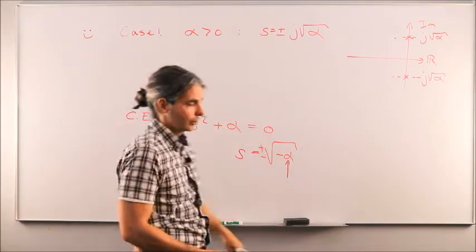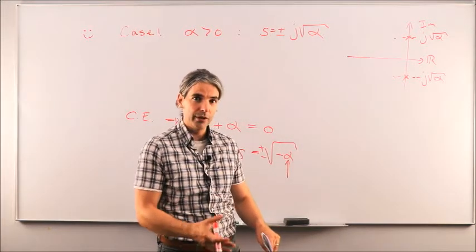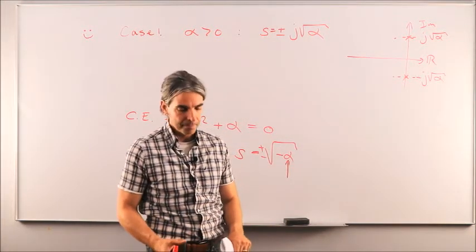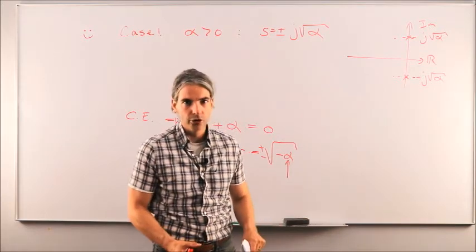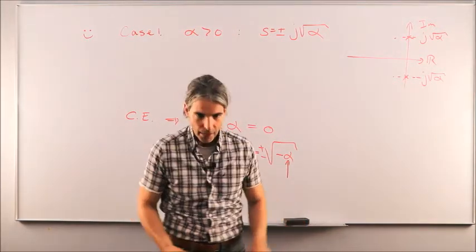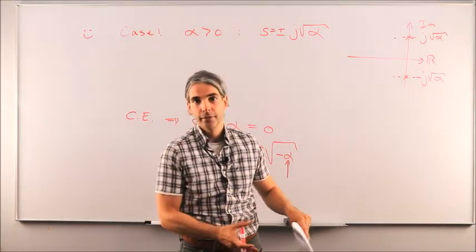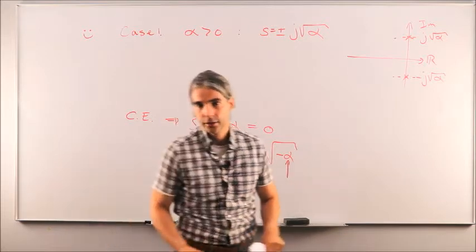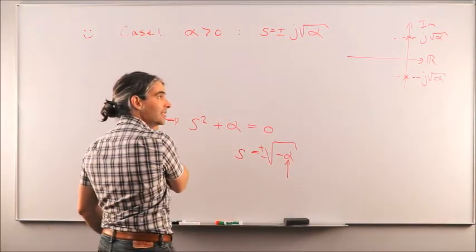While if the pitch starts to deviate a little bit, or if there's a slight deviation between body fixed and roll pitch yaw reference frame, then it means that this deviation in pitch will not grow larger with time. It will just swing back and forth along the pitch axis, or about the By direction, okay? It will never go back to 0.